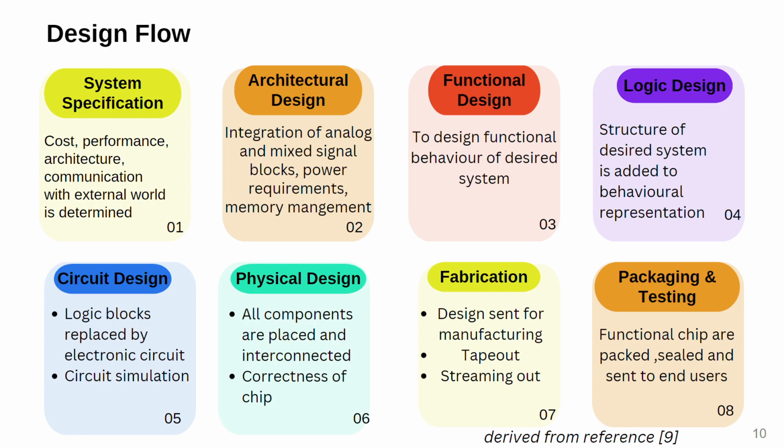And next step is circuit design. The logic blocks are replaced by electronic circuits, which include transistors, capacitors, and resistors. Circuit simulation is done at this stage to verify the timing behavior of the desired system. SPICE is a well-known program for circuit simulation.